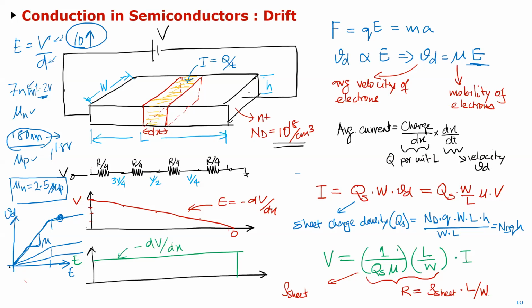So if you want to just take away 3 things, the mobility depends on the type of material. It's N-type, P-type. Why? That's a little bit involved. Even I have to look. It's mostly to do with what's called lattice coefficients, like how much it is banging against the crystal lattices. So to understand the exact mechanism, you have to go a little deeper into that semiconductor theory. But essentially, it depends on the material, it depends on the temperature, and on the electric field also.